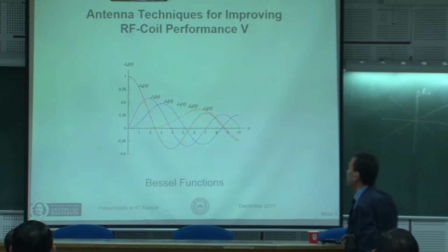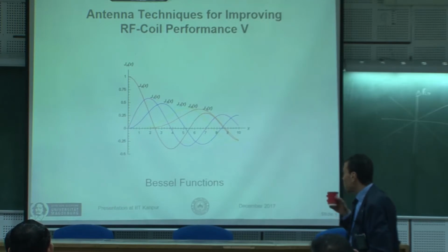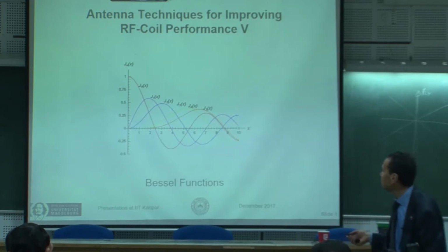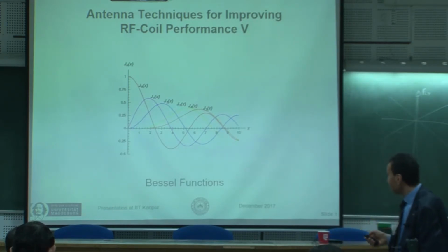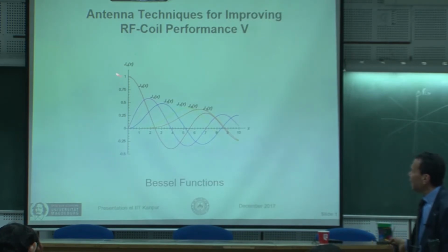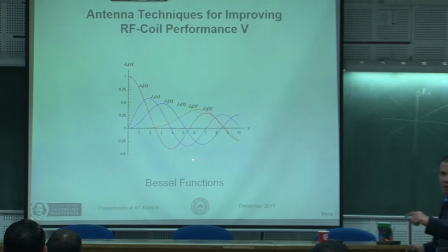Now we come to a known distribution of Bessel functions, just to revive or refresh your information. I need that for my discussion. If you consider the Bessel function of the first kind, J naught looks like that. Important for me is this area here, because I told you X here plays the role of k naught times a, or what's called the electrical length, 2π physical length divided by the wavelength. Important for me is this one here.